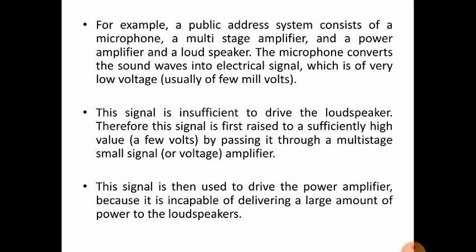In a public addressing system, to convert the sound signal, that is from mechanical vibrations to electrical signal, we need a microphone. But the level of voltage is very low, so it should be amplified using a multi-stage amplifier, in which the first stages are typically small signal amplifiers, that is voltage amplification is done.